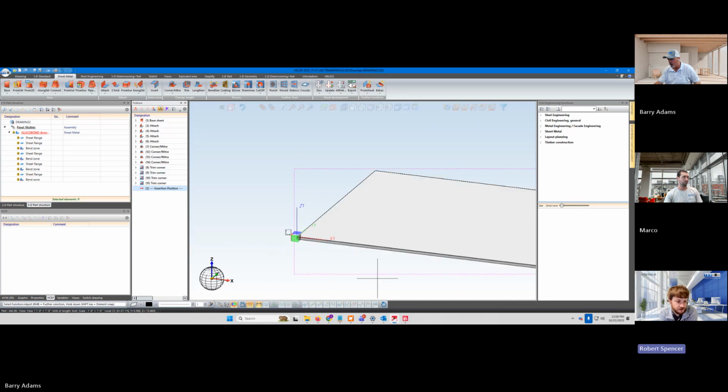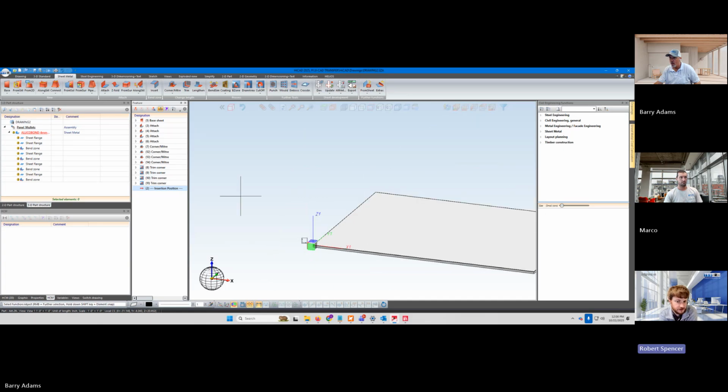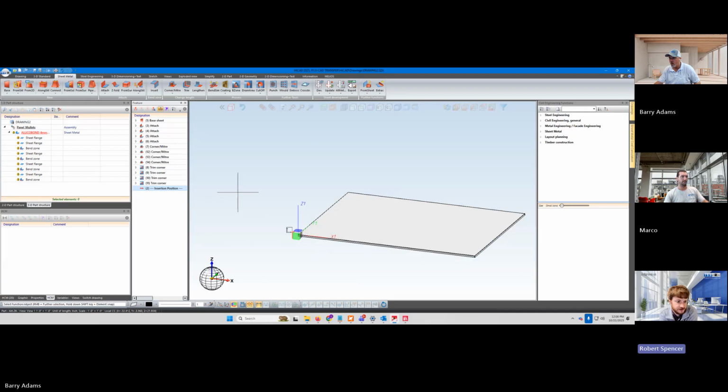A couple things to note here. Notice that the origin is on the front of the panel, and this is, in my opinion, the best recommendation so that the sketch that we're going to apply the element to is going to hold the face of the sketch and work backwards in the Z minus. That way your sketch plane is the front of the panel.